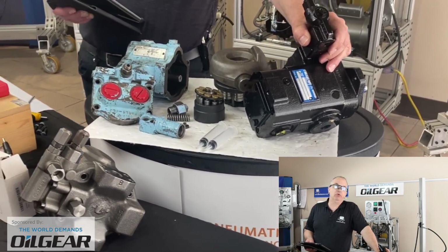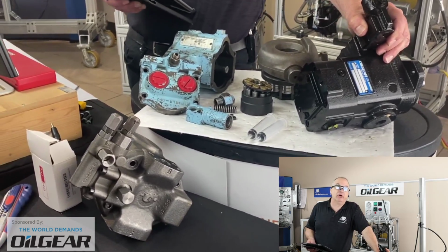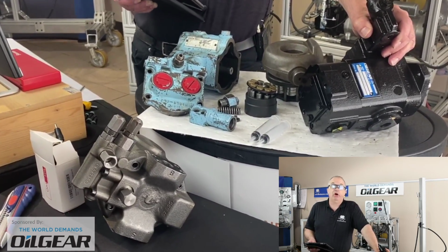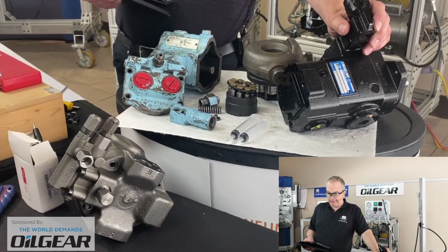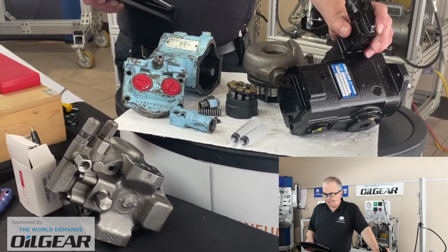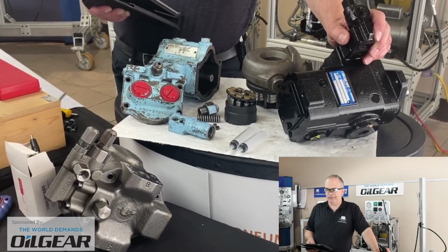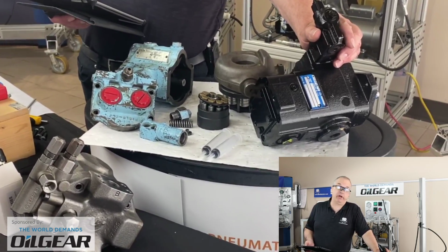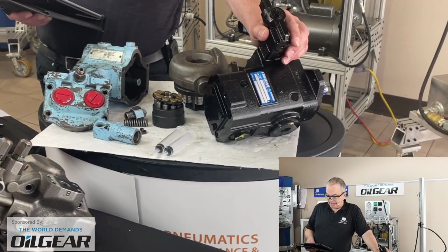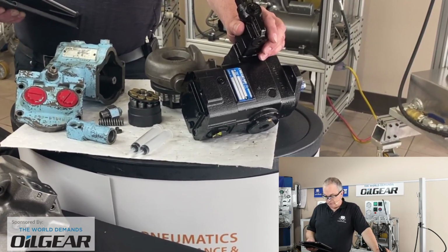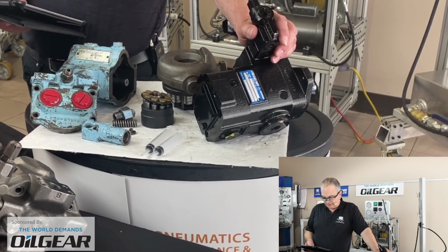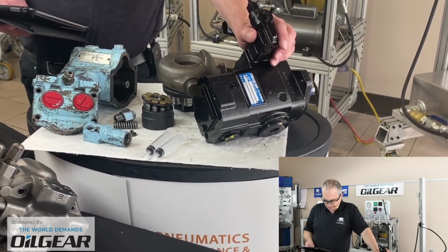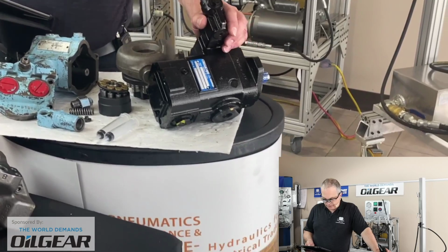I think maybe you want to work with a hydraulic motor that has the minimum amount of internal static friction, a very high mechanical efficiency rating, I guess. Is that the right way to think of it? Anyway, you want to work with a hydraulic motor that spins very easily, so that the flow meter itself doesn't load the hydraulic system. I can't see why that wouldn't work. Very clever.